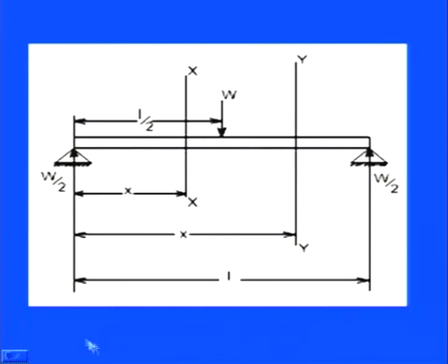So now considering the same part, we have this L length, same cross-sectional beam, and these two reactions which have the same magnitude, W by 2, W by 2, acting in the upward direction. This point load is acting downwards, and because of that we have the shearing action in this portion as well as in this portion. So if you go for the left hand portion, what we are doing here is first considering the XX portion.